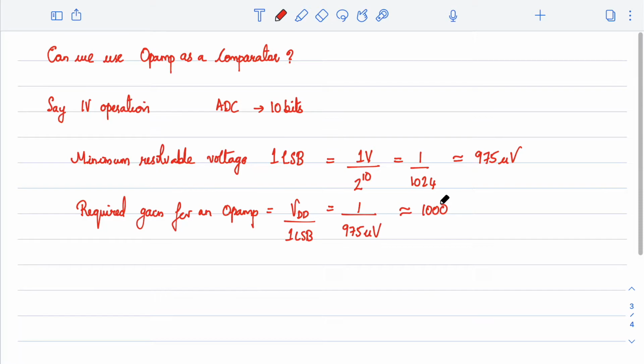Now, in the previous classes, you remember we were discussing op-amps, especially the frequency response. Say I look at the frequency response of an op-amp. This is the frequency axis, and here I can mark the DC gain A0. But we know that an op-amp does not have an infinite bandwidth, rather it has a finite bandwidth. Usually the finite bandwidth, or the first pole, we call it the 3 dB frequency also. That usually defines the bandwidth of the system, and after that we expect a curve like this.